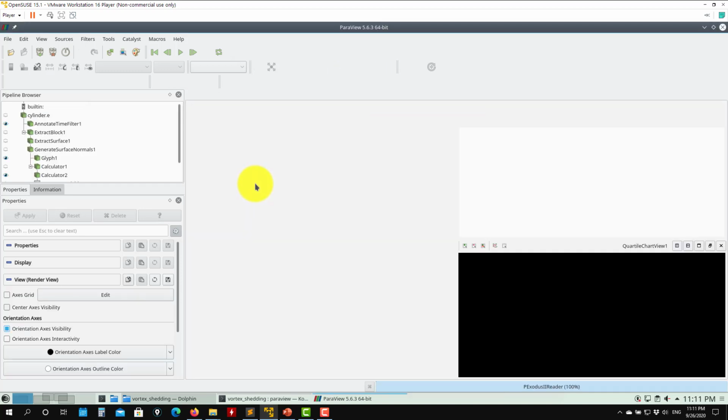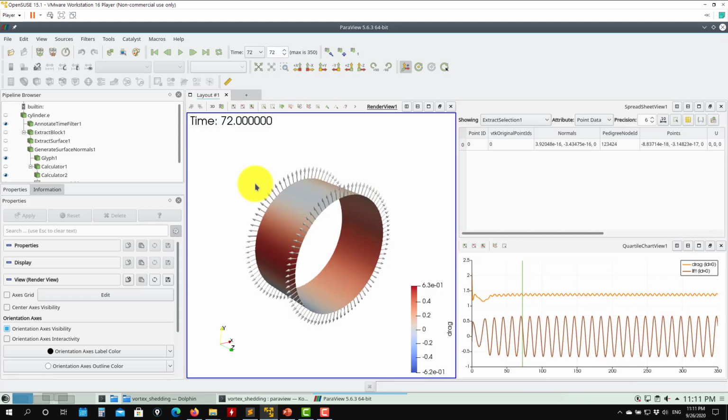Open. So we remember the total forces are the composition, or the contributions, of the pressure forces and the wall shear stress forces. You can compute wall shear stresses here, but it's very time consuming. You need to compute the derivative at the walls, then multiply by the viscosity, then sum. So it's time consuming, so do it in OpenFOAM. I'm not going to show you, but have in mind that you can do it with no problem.